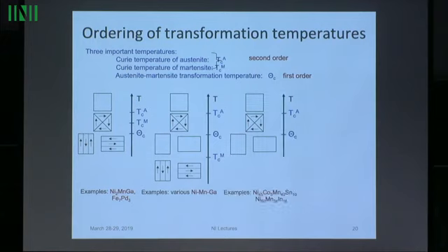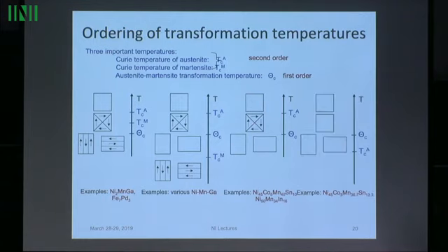We have examples of that. You could have a material which is ferromagnetically ordered in austenite, transforms and loses magnetism altogether. And you could even have a material, I'll show you one very interesting material, in which it has no ferromagnetism at all. Okay? But secretly, the austenite phase, if it did not transform, would have ferromagnetically ordered down here somewhere. Okay? So that could be true. You just don't see it, right?